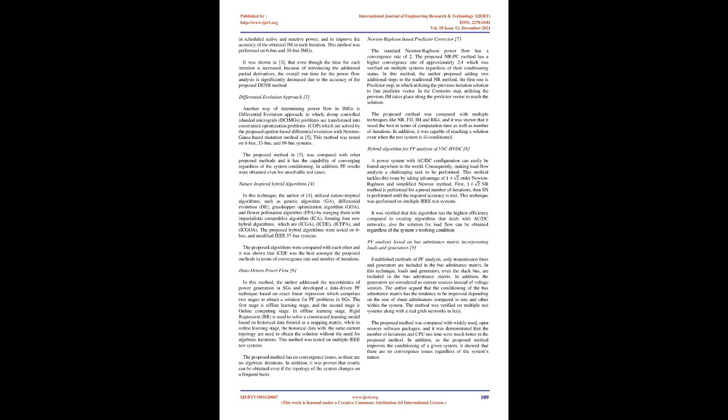Newton Raphson-based predictor corrector [7]. The standard Newton Raphson power flow has a convergence rate of 2. The proposed NRPF method has a higher convergence rate of approximately 2.4, which was verified on multiple systems regardless of their conditioning status. In this method, the author proposed adding 2 additional steps to the traditional NR method.